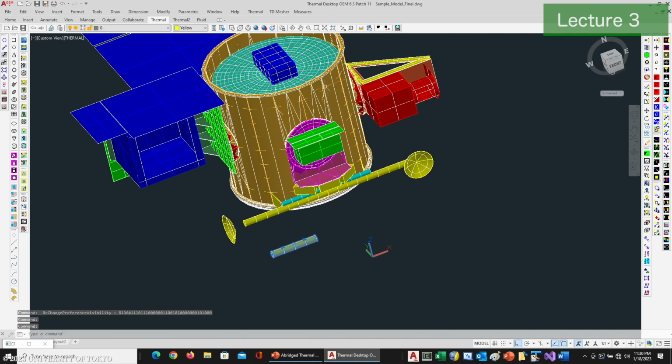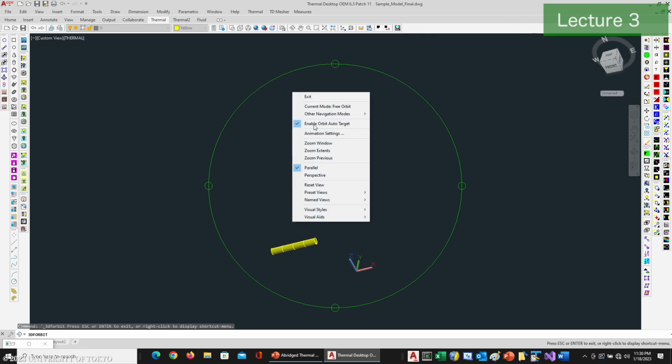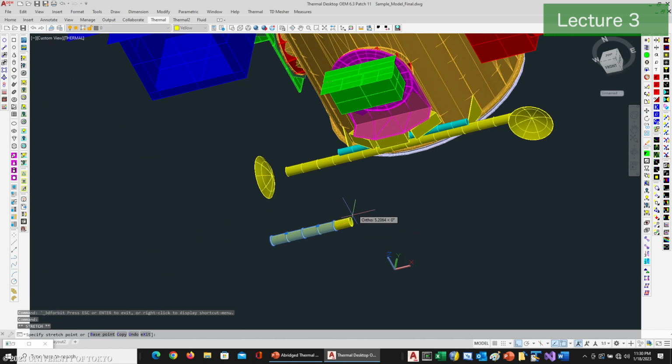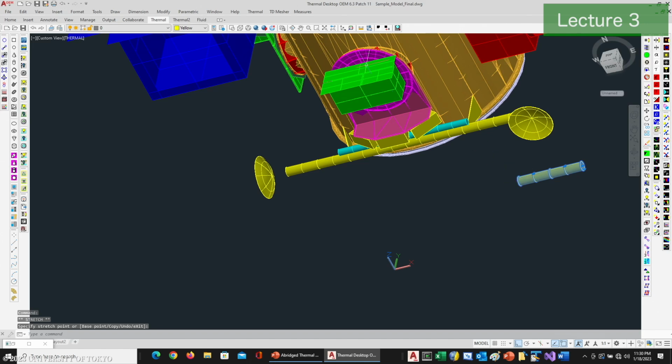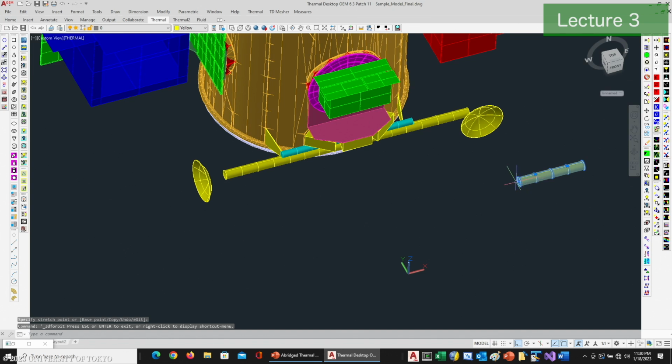So I'm going to use the grips and extend this to the other length. Oh, that's the origin. Okay, another trick. I'm going to move this along here. I want this to line up, so I'm going to move this along here. I'm going to take this end here and extend it to the end point of here. Okay, that's now made it this long.